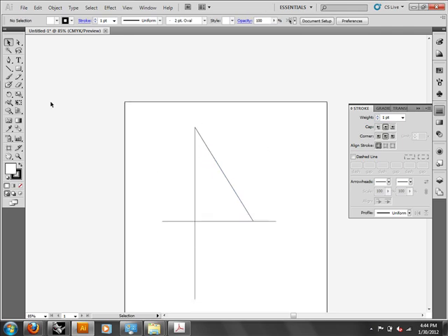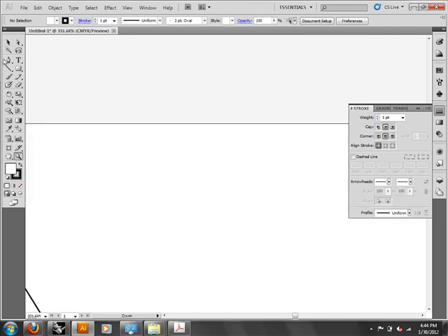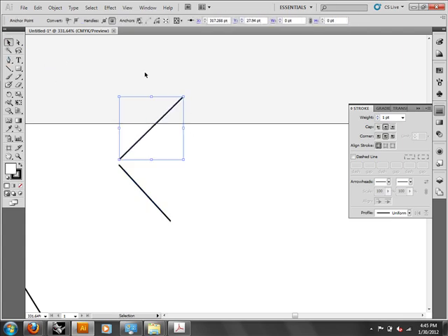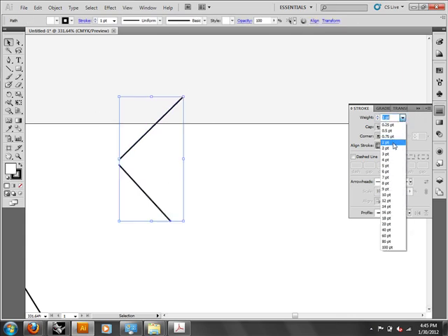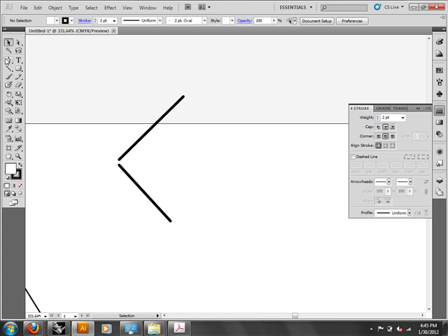But that's the idea. Also, a big thing, a reason why that might be happening is that your lines aren't actually joined together, and so you might need to go with the pen tool and just heal those corners. Okay, just kind of fix those corners together. If you've got 2 points, for instance, that are like that, and we're just going to beef these up here. You might need to go in and just heal them up. You know, just kind of quickly fill that in, and then when you zoom out and they're big enough, it might fix that. Or you could take the point and move it with the direct selection tool. You can just kind of snap it to that end.